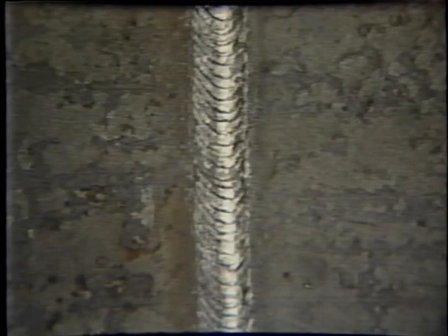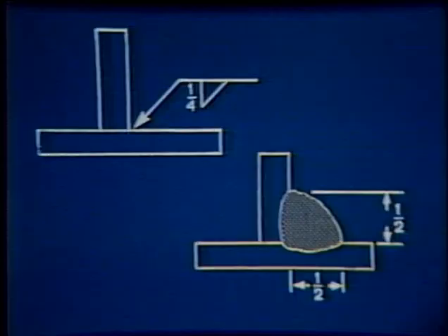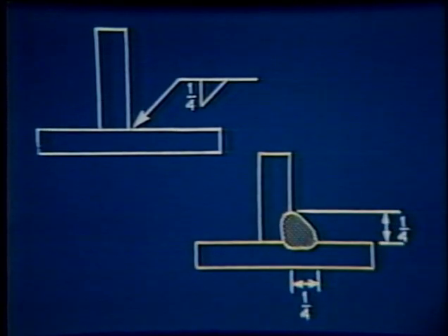Excessive reinforcement can be prevented if the procedure is followed and the welder can demonstrate the ability to weld in accordance with the procedure. Another common discontinuity that can lead to weld failure are welds that are incorrect in size. When working to codes and standards, tolerances can be very precise. The amount of precision is based on the code and the design of the particular weldment.